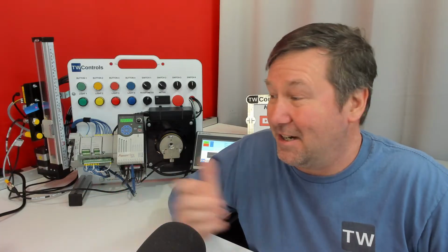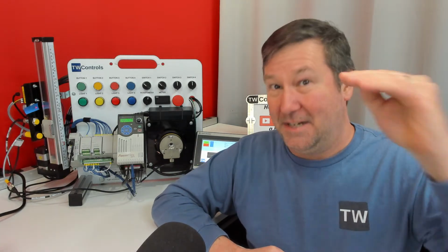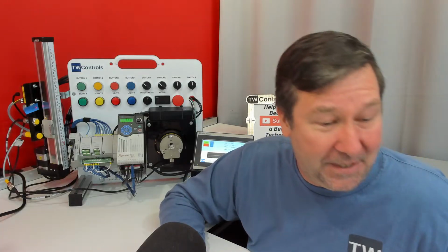So I'll have somebody say, yeah, it always seems to be searching. And I'm always like, okay, is it kind of sinusoidal, like ramping up and down, or is it like up, down, up, down? They're like, it's up, down, up, down. And I'm like, 100%, I know somebody has dropped an integer somewhere in there and you're having a rounding error. So that drive wanted to run at 49.3%, but since somebody put an integer in there, it's going to jump between 49 and 50, 49 and 50.